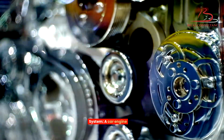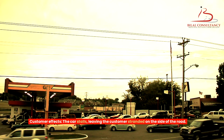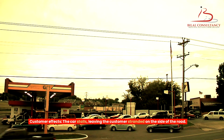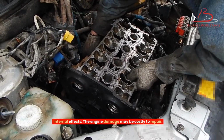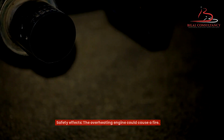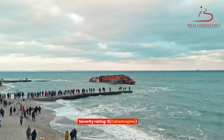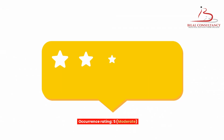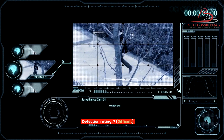System. A car engine. Failure mode. The engine overheats. Effects. Customer effects. The car stalls, leaving the customer stranded on the side of the road. Internal effects. The engine damage may be costly to repair. Safety effects. The overheating engine could cause a fire. Severity rating, 9, catastrophic. Occurrence rating, 5, moderate. Detection rating, 7, difficult. RPN, 315.